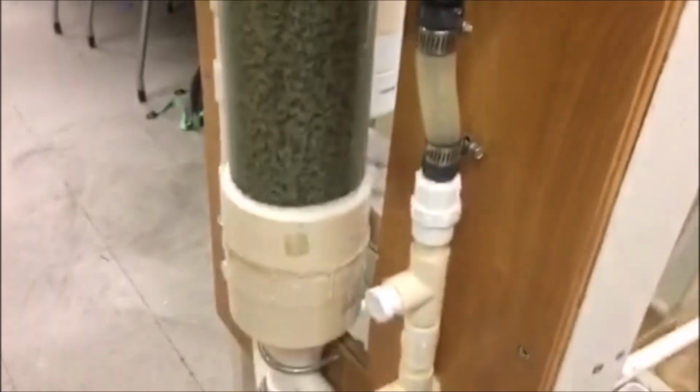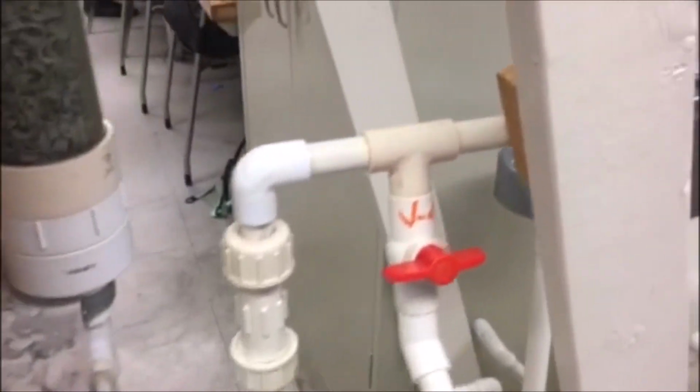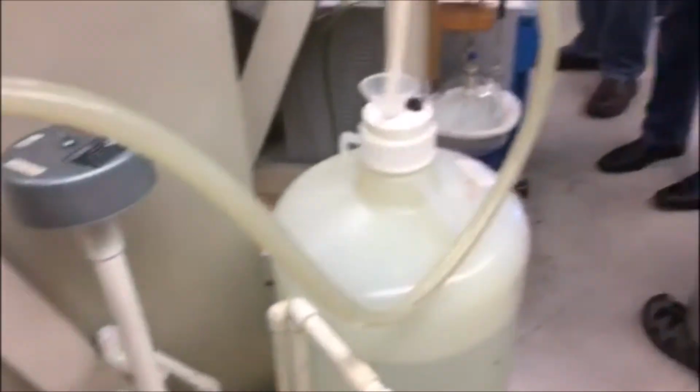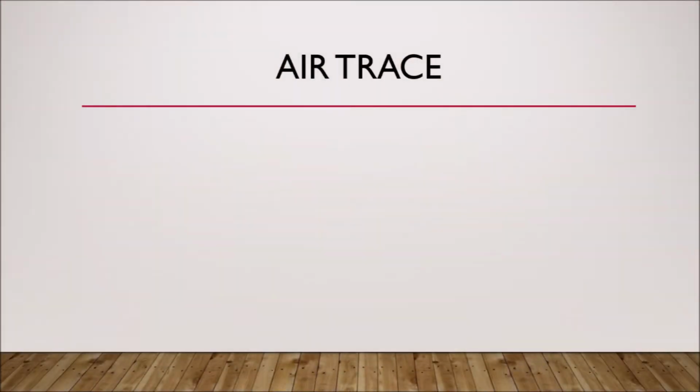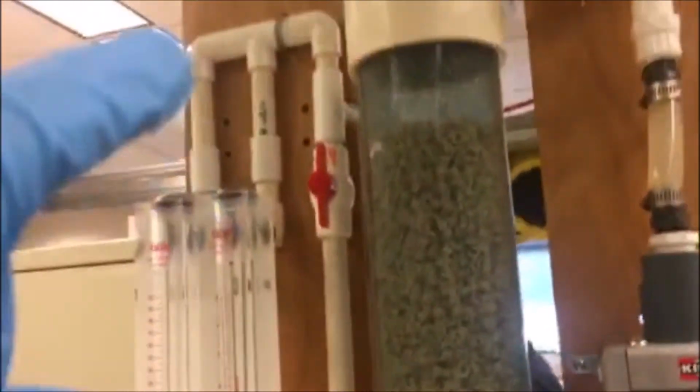As the gas strips the ammonia from the liquid, it exits from the bottom and is recycled back into the tank. There is a purge stream within the recycle stream. This is where the samples are collected for the exit liquid stream. When it comes to the gas stream, we are using air to strip the ammonia. Therefore, air is going through the compressor, then set up the gas volumetric flow meter. It is then guided to be sent through the bottom of the packed column. As it travels up through the tower, the gas outlet is led towards the fume hood.